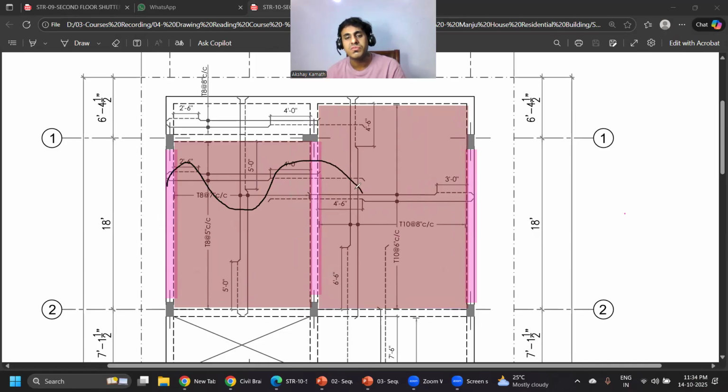Okay, now I'll finish it off. Then again, it will sag like this. Then again, it is going to have a negative bending moment like this. If I draw one line between them like this, we have a negative here. Negative means this portion tries to lift up. We have a positive here. This entire thing is negative, positive and negative.